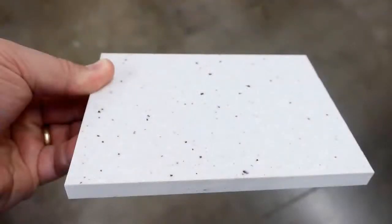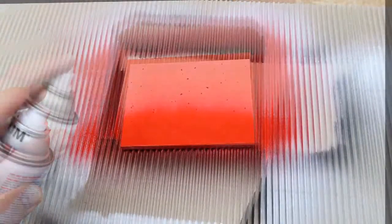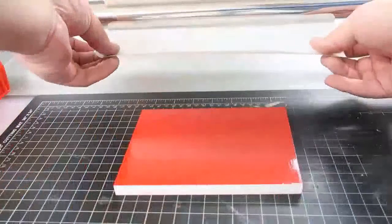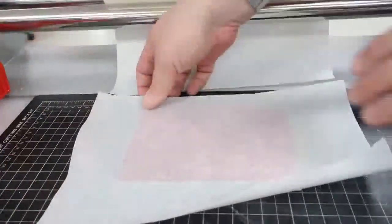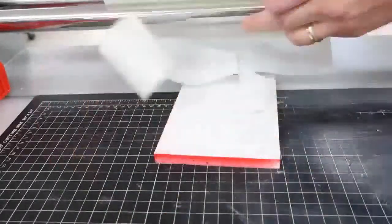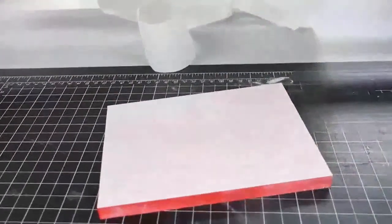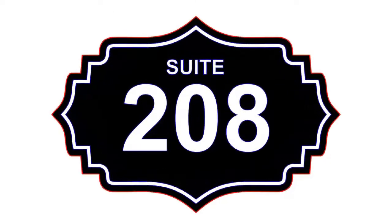So here's a sign where I'm going to take a piece of the Avonite solid surface material and I'm going to just paint the surface. And the reason I'm going to paint the surface is because the contrast on this material is kind of low. So I'm going to paint the surface first, and then I'm going to apply a transfer tape. Transfer tape is just going to protect that paint for the process of the lasering. So then we're going to take that and stick it in the laser system, and then we're going to engrave this graphic.